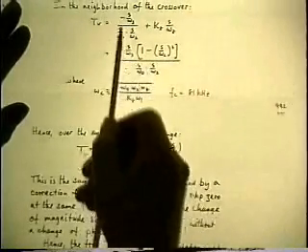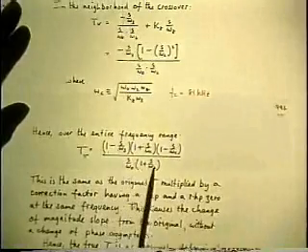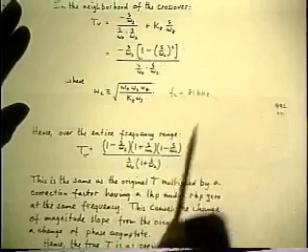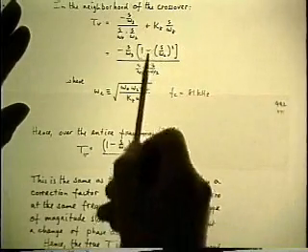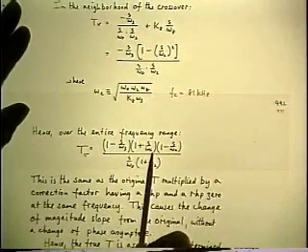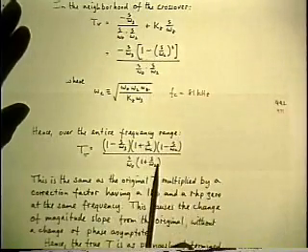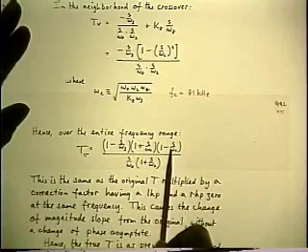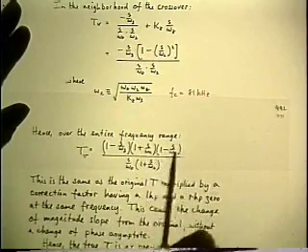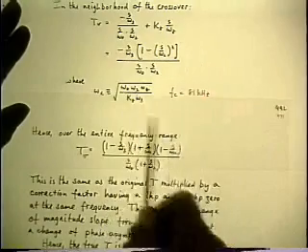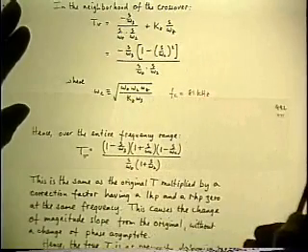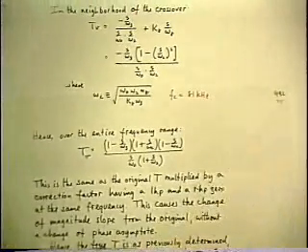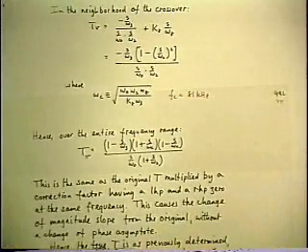So here is the restored T in front, and here is the square bracket, which is the correction factor that I just solved for, and I can factor it immediately because there's no middle term. And it factors into a left half plane 0 and a right half plane 0 at the same frequency omega c, which I also know analytically, and I put the numbers in, and it's 81 kilohertz. Now that explains everything that was measured.